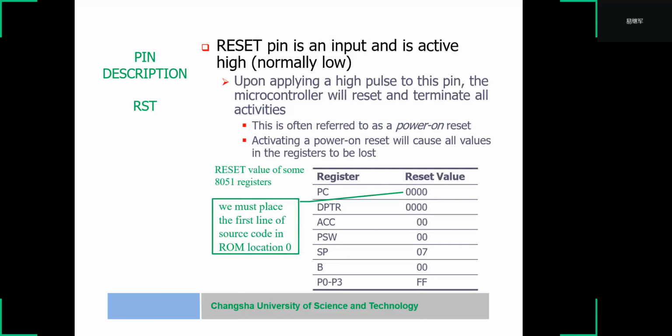The reset pin is an input and is active high. Normally it is low. Applying a high pulse to this pin, the microcontroller will reset and terminate all activities.